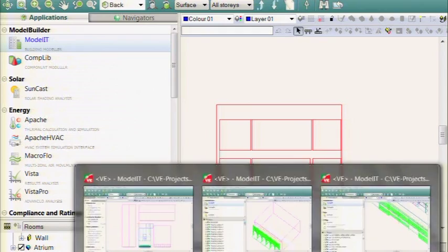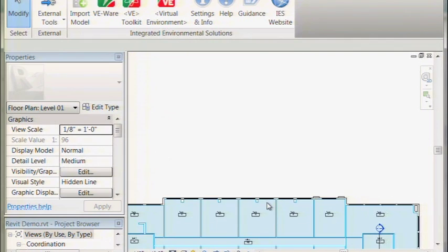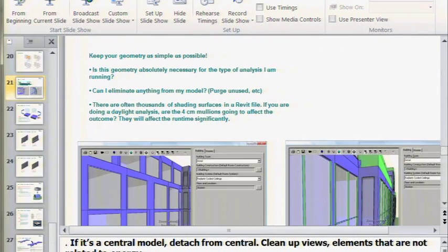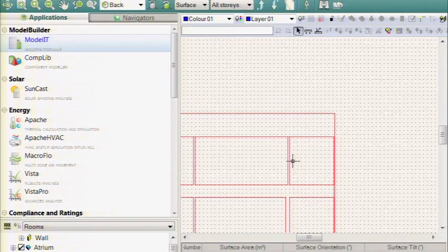And the only time that inner volumes are not read from the constructions of the material itself are when you pull it in from Revit or thick-walled modeling with SketchUp. If I'm inside of the VE and I actually turn off my inner volumes and then rebuild them, they will look almost completely different, because then it is based on the construction. So if you have set up your inner volumes in a way from Revit specifically, make sure not to turn them on or off, because it will rebuild them with a different view.